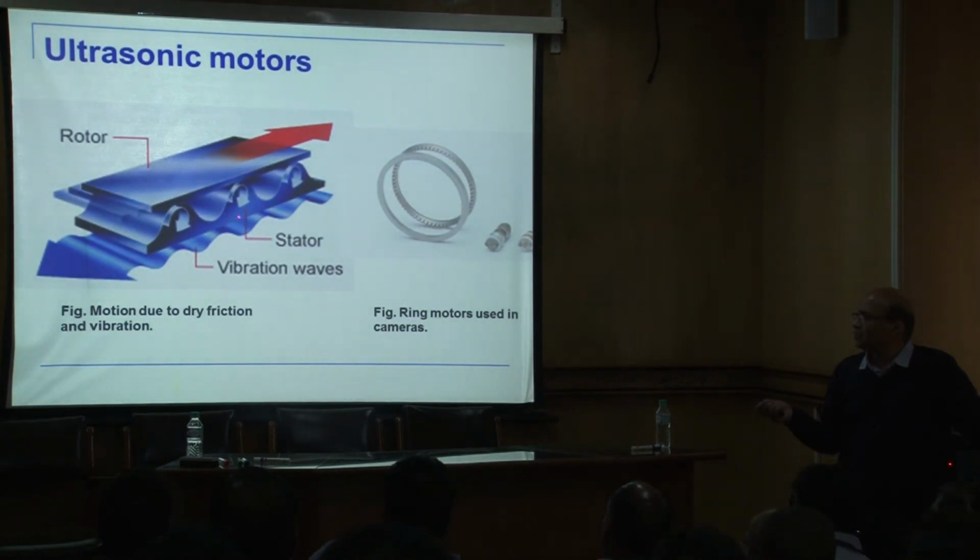We have a rotor and we have a stator. Now, the stator is made up of piezo crystals, and this is the rotor, and this is in physical contact. Now, how it works is, this fellow being piezo, if you charge it, if you activate it in a particular sequence, in a particular frequency. So here, if I charge this one, what will happen? It will give a small kick there, or a small push there. It will move this side. So I'll activate this one, then this one, then this one. So what will happen? This fellow will move in that side. If I reverse it, it will move this side.